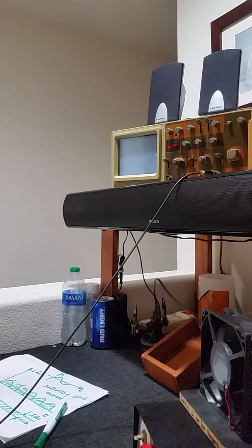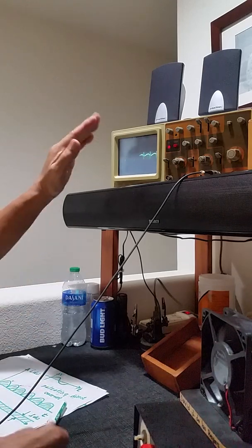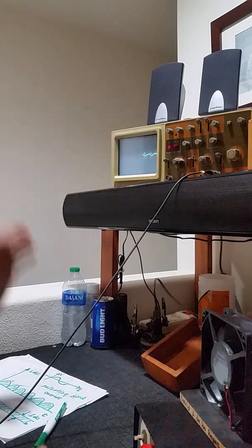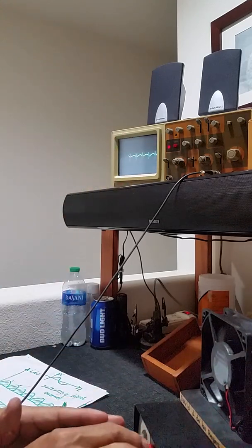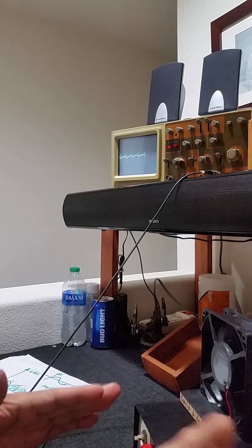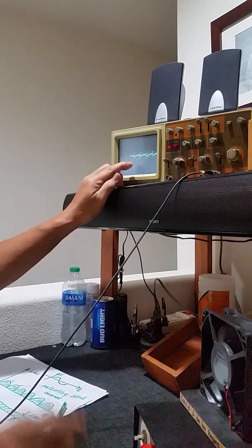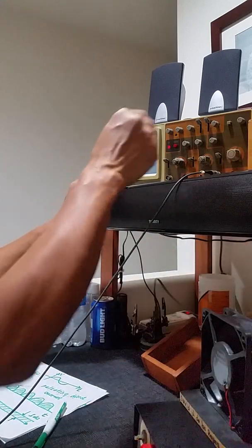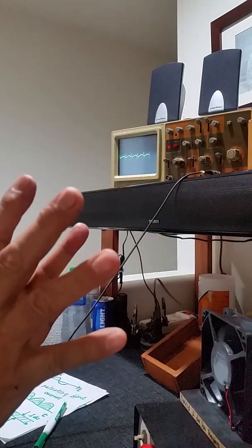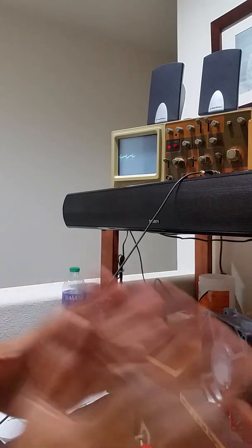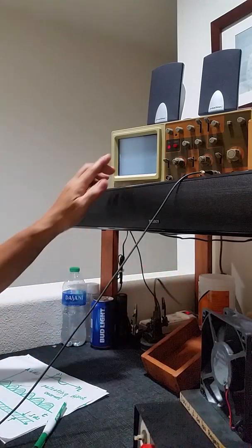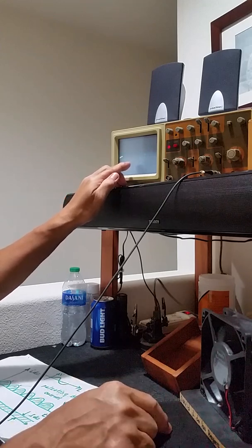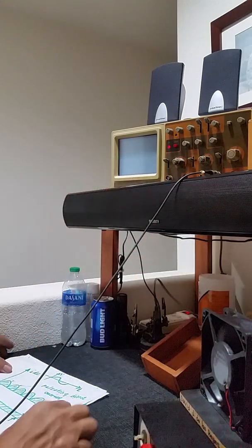So as I place the ground connection and the probe connection, the graph will come out. Whatever graph the output terminal is giving out, that's it. If it's an alternating circuit, it should be alternating. The next time around, I will show you the graph of an alternating current. But for the meantime, this is a pulsating direct current. It's the output of the power supply that supplies our gadgets.